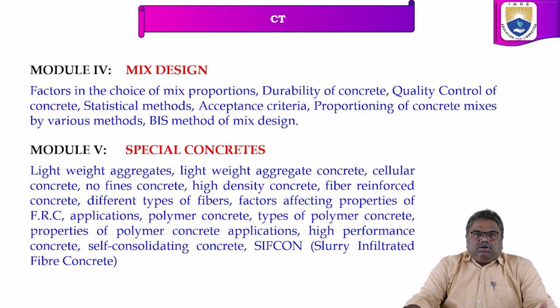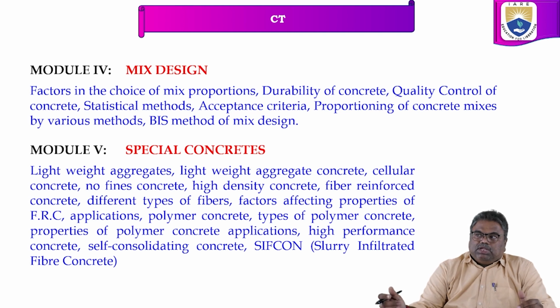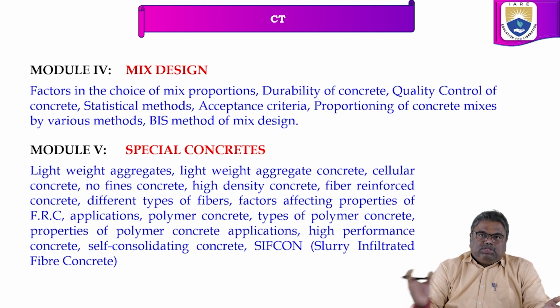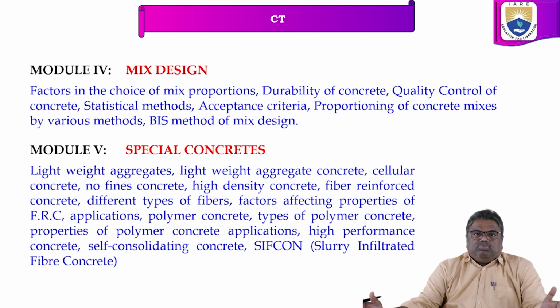For example, a ready mix plant is 10 kilometers away from the site. We have to carry the concrete from the ready mix plant to the site. During the travel time, the concrete should not settle within these 10 kilometers.